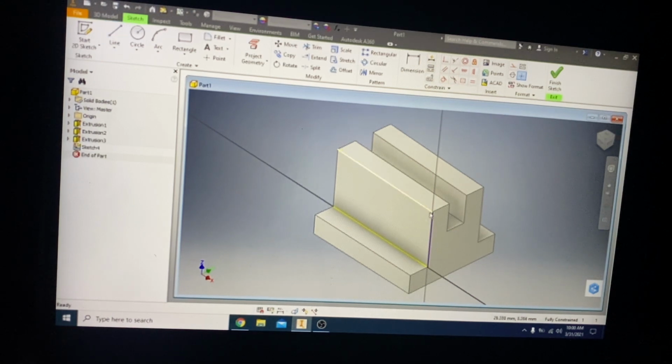Now I need to go inside, because it is a non-isometric line. Line inside is how much? The dimension given to us is 30. Click there, go inside 30. Angle is 180 degrees, type 30. Enter. Now I have finished drawing that line.